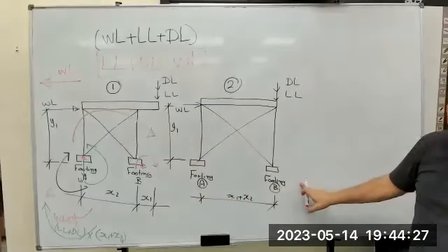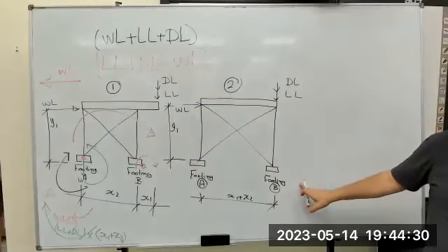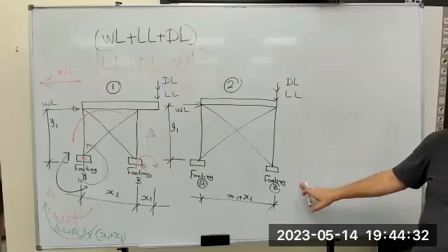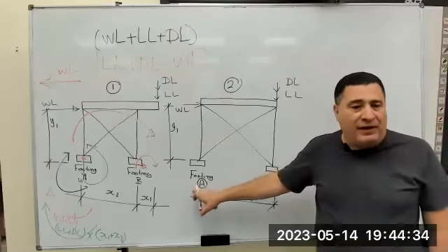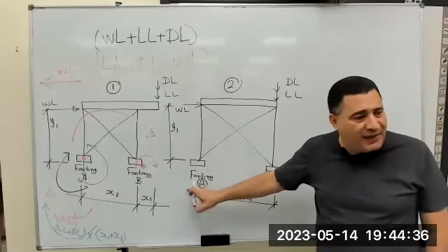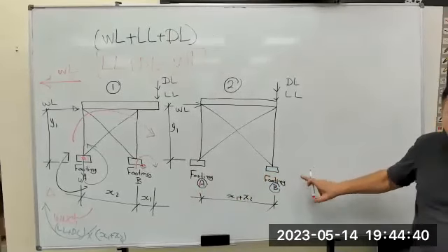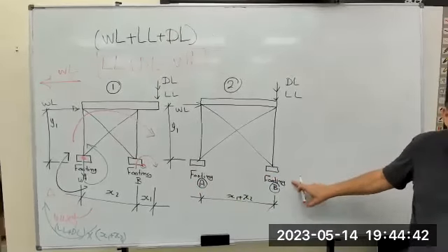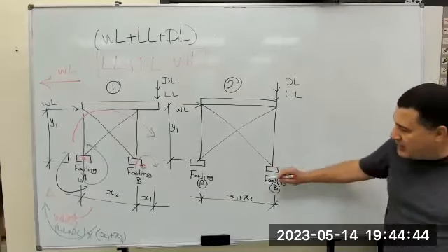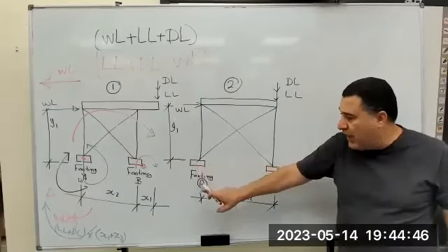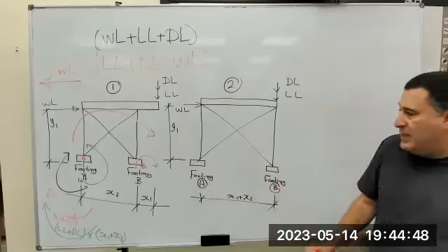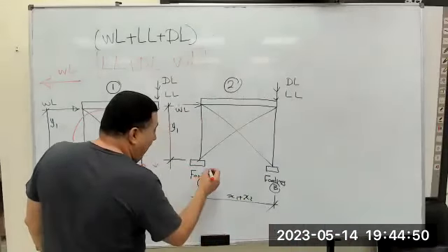Now this system is more stable for overturning, but uplifting is still there. Overturning here is more safe. I make it more safe. Increase the foundation for footing A, and you are more safe, and instead you have foundation to avoid uplifting.